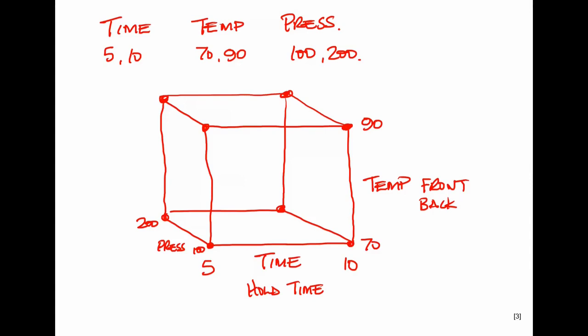You're going to create a cube, a design space, and that is what a designed experiment is, and it is nothing else. If you've logically decided using your skill, that's just a 1-factor test using your skill. And by the way, you'll find out very little using that type of testing. Only these types of tests give you true process knowledge. So that's what a designed experiment is.